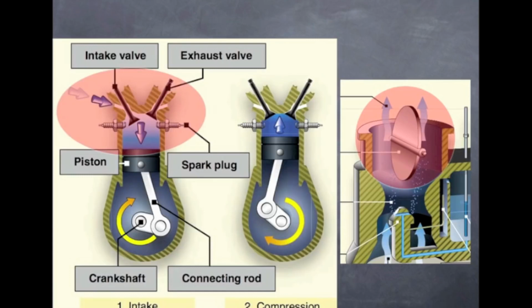So as we throttle the engine, the actual cylinder is going to pull down and create a vacuum within the intake manifold. Therefore, our pressure in the intake manifold is usually a negative compared to the outside. It's less than the outside pressure. And that is where we measure our manifold pressures, at the intake manifold.